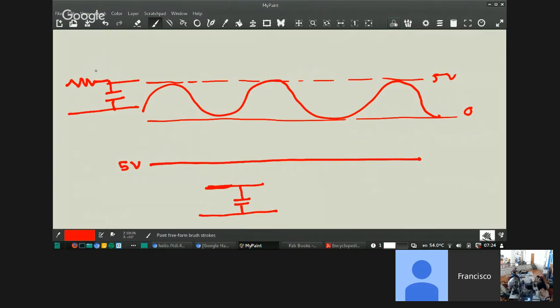So what you draw over there, that's perfectly fine for a signal line. Depending on where you put the components, you saw two configurations over there, right? In one the capacitor was grounded and in the other the resistor was grounded. That's like a low pass and high pass filter. Okay, so understood.